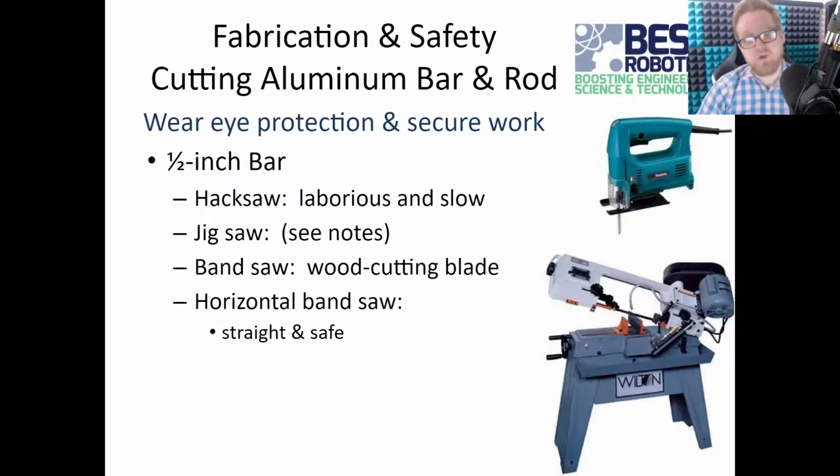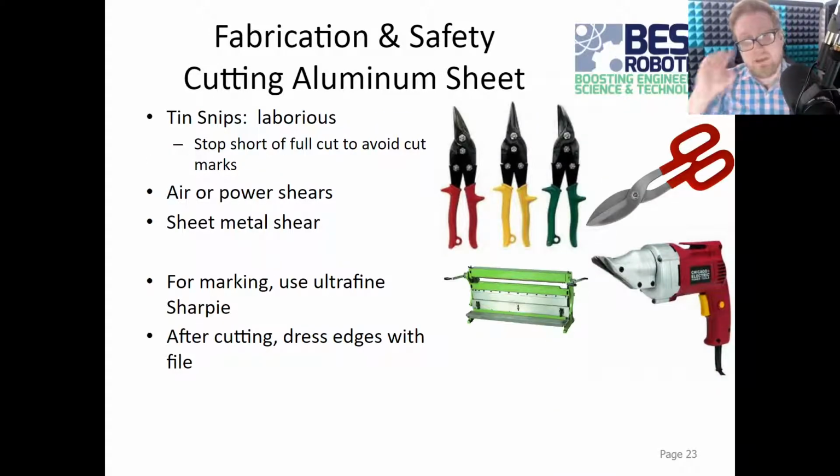Honestly, if you can avoid using a bandsaw for the aluminum sheeting at all, that is recommended, which I think is our next slide. Yep. It is not recommended, just because for bandsaws, you want to make sure that the number of teeth you have on the blade is usually 2 or 3 for the height of the material. And even when you go to a metal bandsaw blade, you will usually not have enough teeth for the sheet itself. So there's a couple of other ways you can work with it.